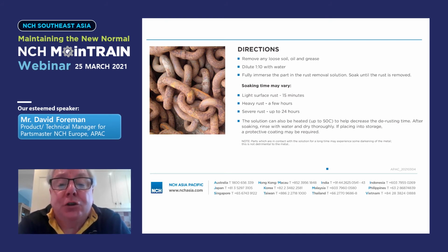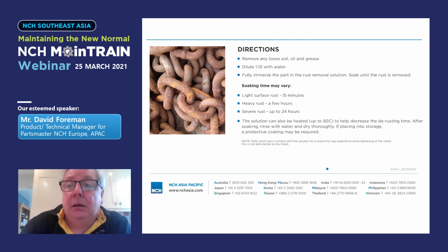You will have to treat the derusted components within 48 hours of applying Xrust 7. And that is another important point. Unlike acid-based derusters, Xrust 7 gives a protective layer on the component for around 48 hours, by which time you can either put a resistant oil or some other coating over the top to prevent corrosion occurring again. But this is designed for components that can be dipped, okay, that can be put into a tank.